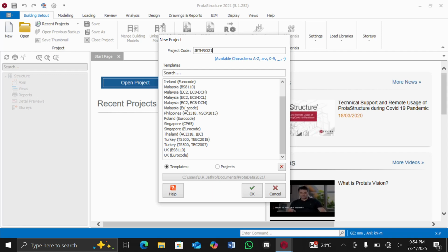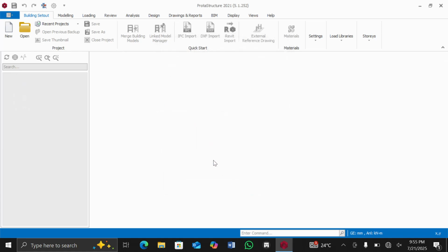But for this video, we're going to use BS 8110. Another person can choose Eurocodes, anything that is compatible with what your country uses is what you are supposed to use. So you come to, as you can see, UK BS 8110. You just come here and click on it. After clicking on it, of course, you just come here and click OK. Of course, it's opening our working area.